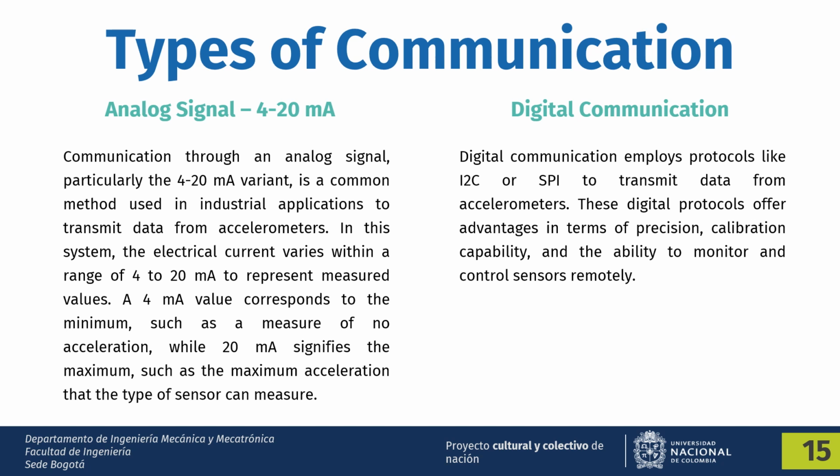Accelerometers with a digital interface can communicate over either SPI, which means serial peripheral interface, or I2C, inter-integrated circuit communication protocols. These tend to have more functionality and be less susceptible to noise than analog accelerometers.